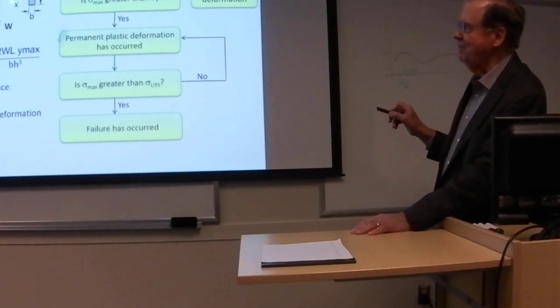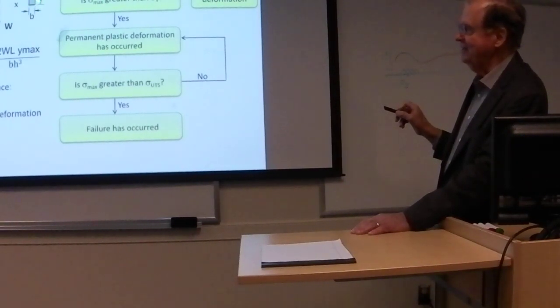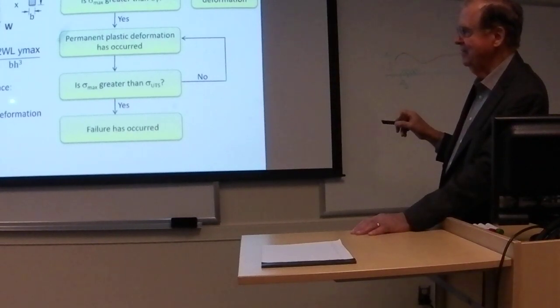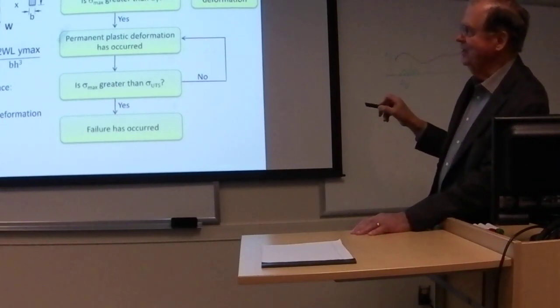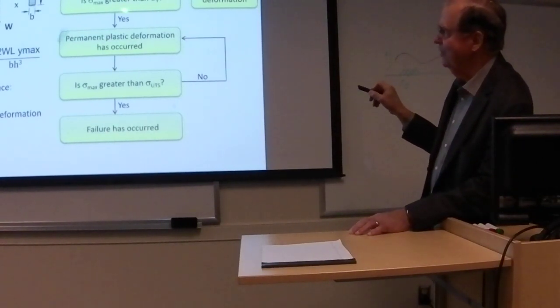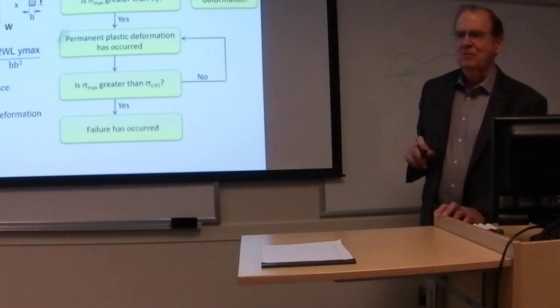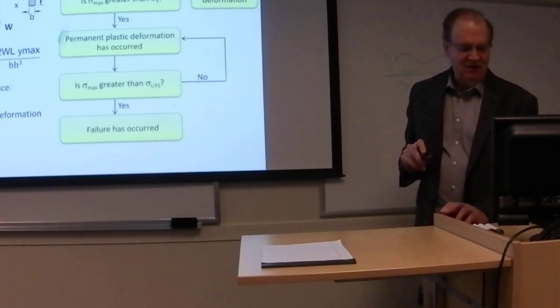This is a very common type of analysis in structural mechanics, and we have a formula for computing that, where the stress is equal to W times the length of the beam divided by I, the moment of inertia, given by this formula here. So it's a simple formula for computing whether the stress yields permanent deformation or even failure.